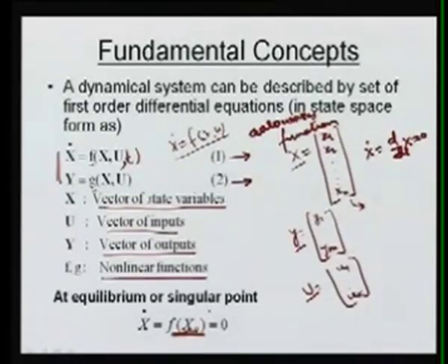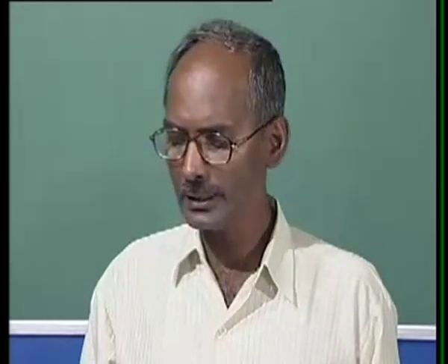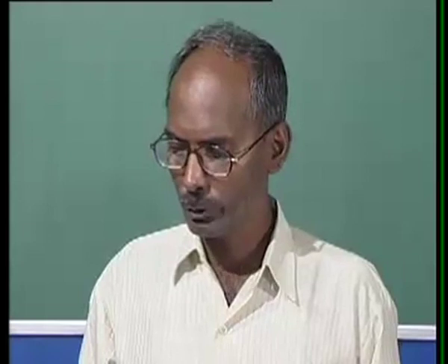Now the question comes into the picture, why is this x there at all? So let us see what the states of any system are. A state of a system represents the minimum amount of information about the system at any instant in time t0 that is necessary so that its future behavior can be determined.